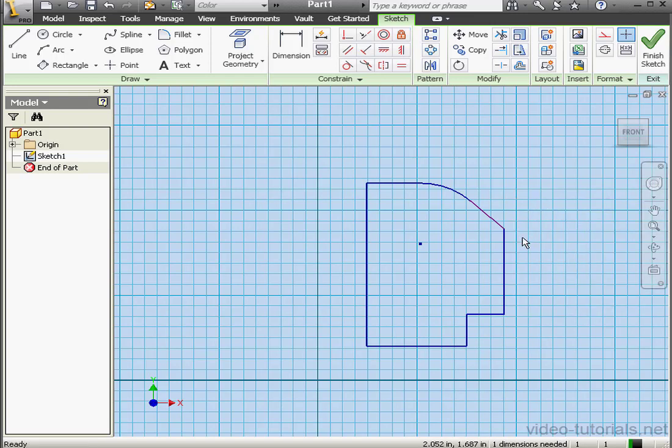Right-click and Done. Once again, to see where I need constraints, I'm going to click on any remaining purple segments, like this corner. I'll drag it. We can tell which part of the sketch moves. That's what needs constraining. Let's undo our movements. Apply a Fix constraint. Click this point here. Now the sketch is in dark blue line and fully constrained as indicated in the status bar.